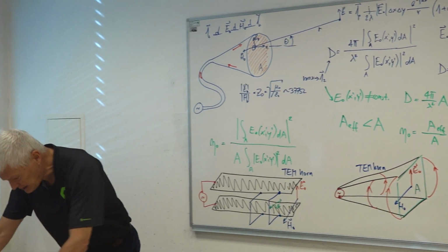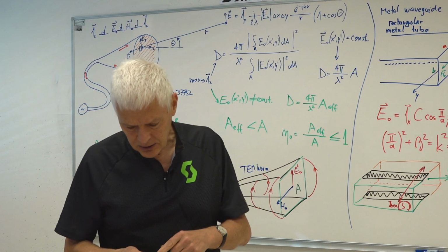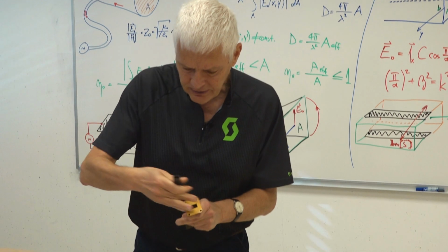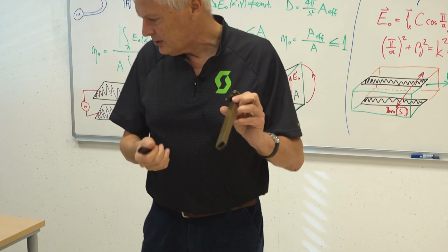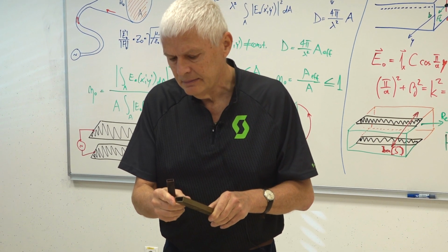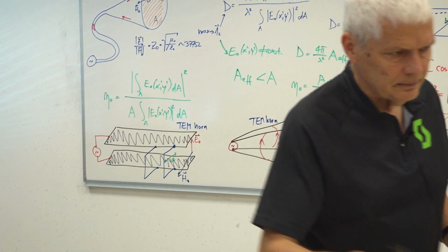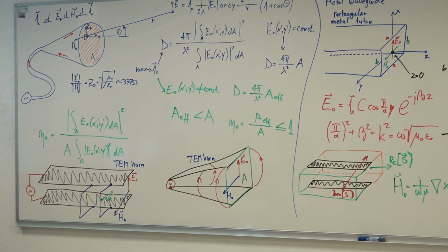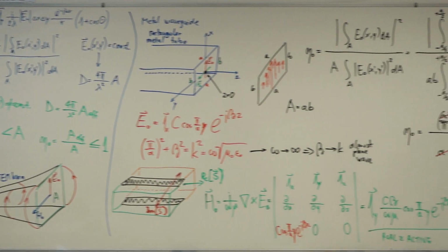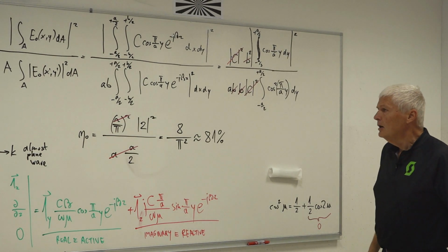And in fact, we have such antennas here. This rectangular copper tube is a waveguide. This is a flange to connect to other waveguides, but these are not the same size because they are for different frequencies. And this is actually an antenna. It's not such a bad antenna. An open end of the waveguide is not such a bad antenna.